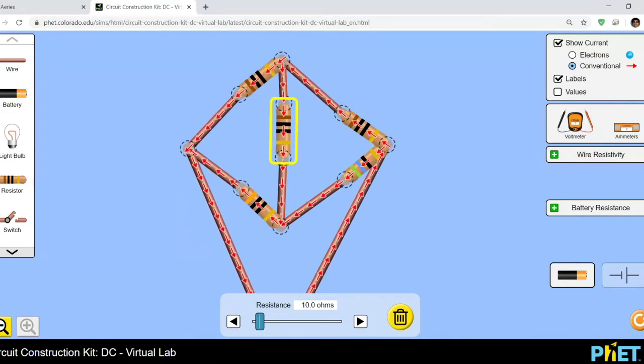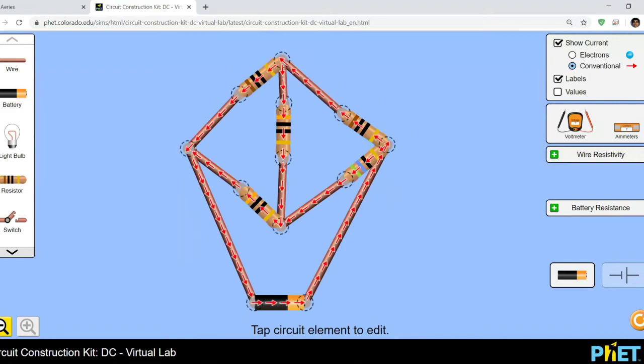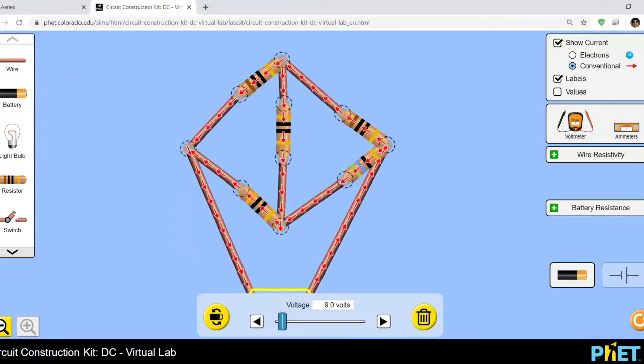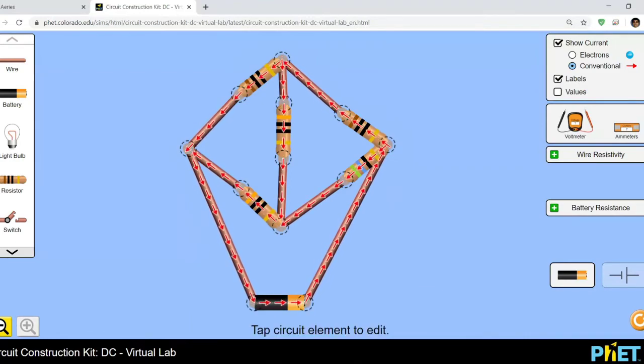This is 30. Okay, so a little bit of current. So now it looks like it's downwards. So that means when you solve this problem, you're going to get a negative current for I5, and that negative current will tell you that you chose the wrong direction. We had it right the first time.